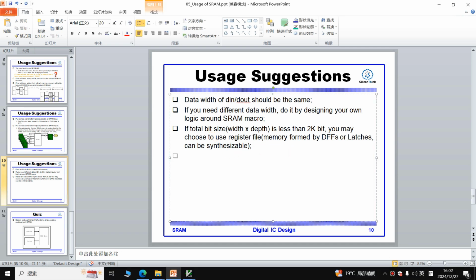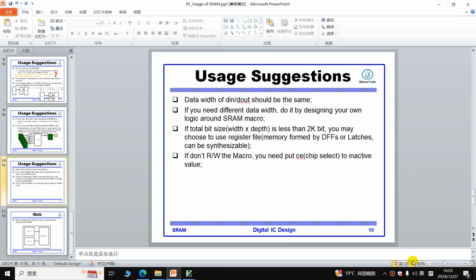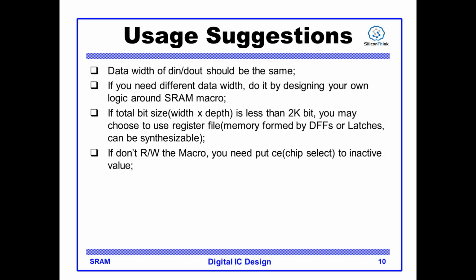And I want to add one item. If you don't read or write the micro in some cycles, you'd better put the chip select to inactive state.